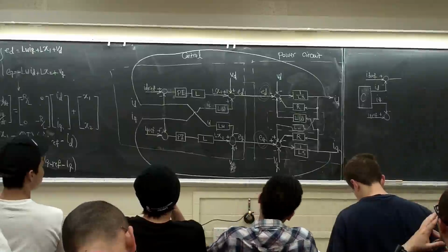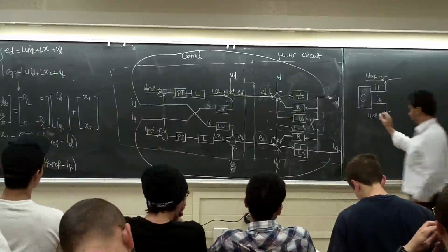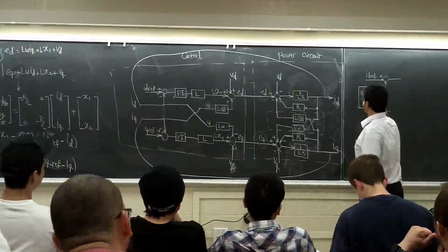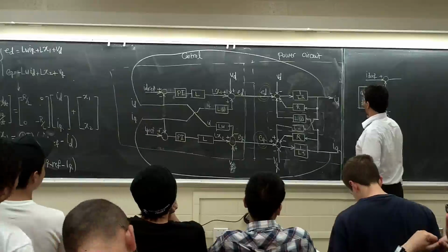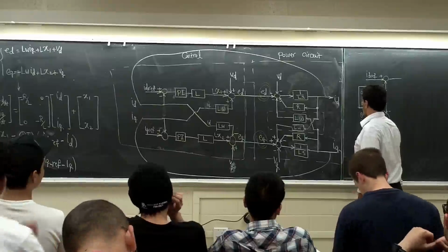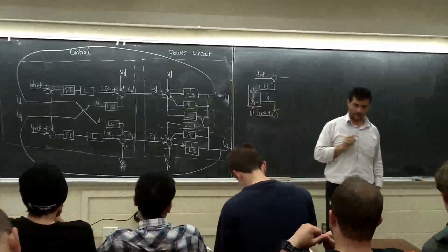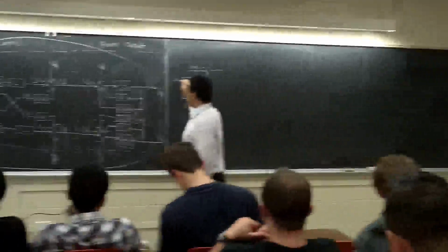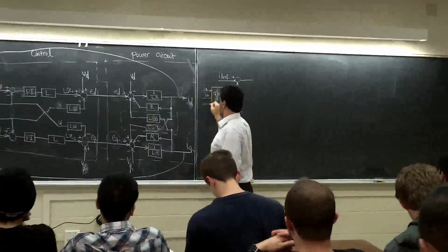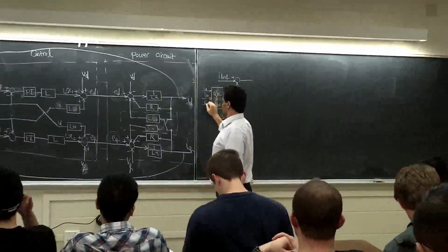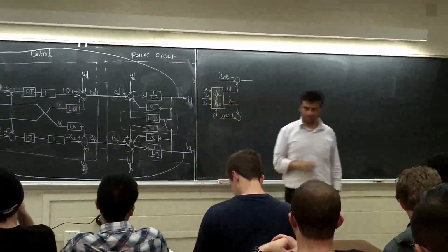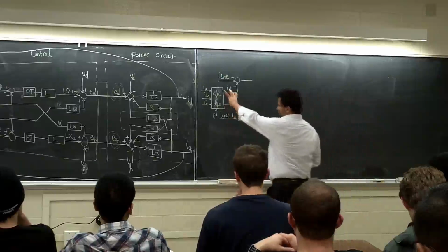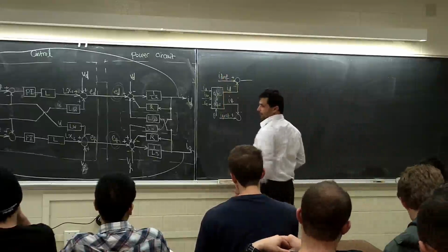A, B, C to D, Q, O. I use the matrix C. Let's put it I, A, B, C to D, Q, O, and I should have a theta input, right? We need to have a theta here. We need to bring the IA, IB, IC to this block. We sense it from the circuit and bring it here, right? Now I have my ID, IQ, I know my references, right?